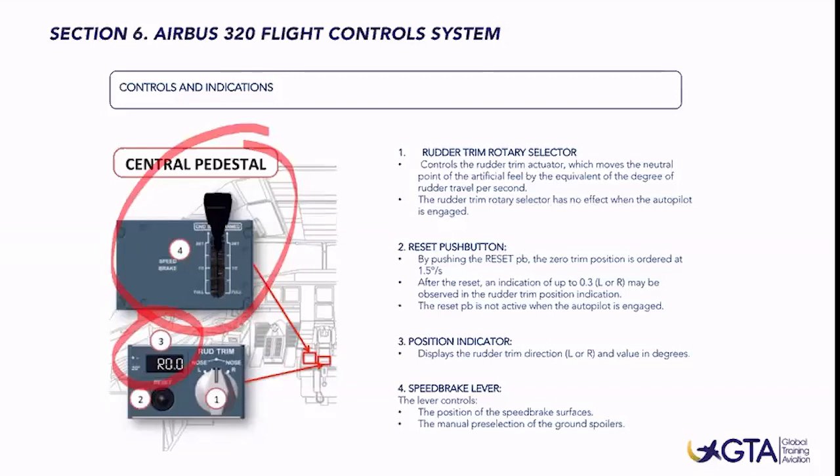This rudder trim indication in flight, say flight level 370, normal speed Mach 0.77 or 0.78, wings level, no failures, should be between 1.0 right and 2.3 left, which means that the actual rudder deflection is plus minus 1.5 degrees.